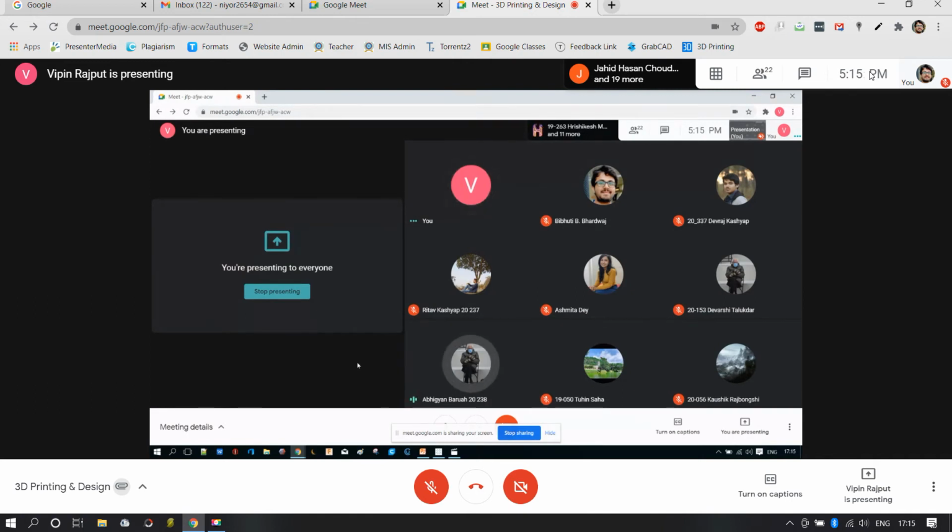Sir, in the last part of the video, what solution did they dip it in for cleaning? Okay. So the particular solution was water. None other than that. After printing and UV curing, you are not supposed to use any chemical over the particular model. What you can do is simply wash away the sanded parts with water. That is the only possible thing you have.